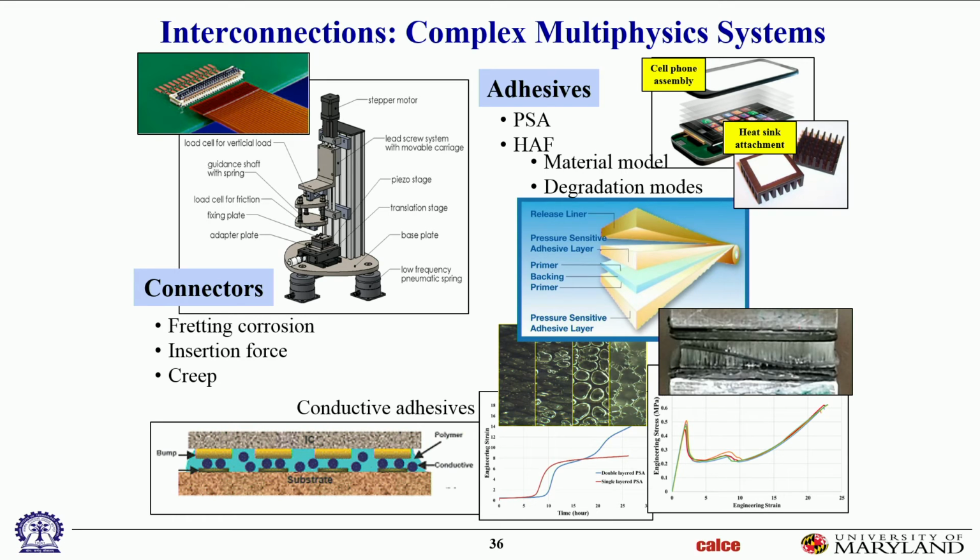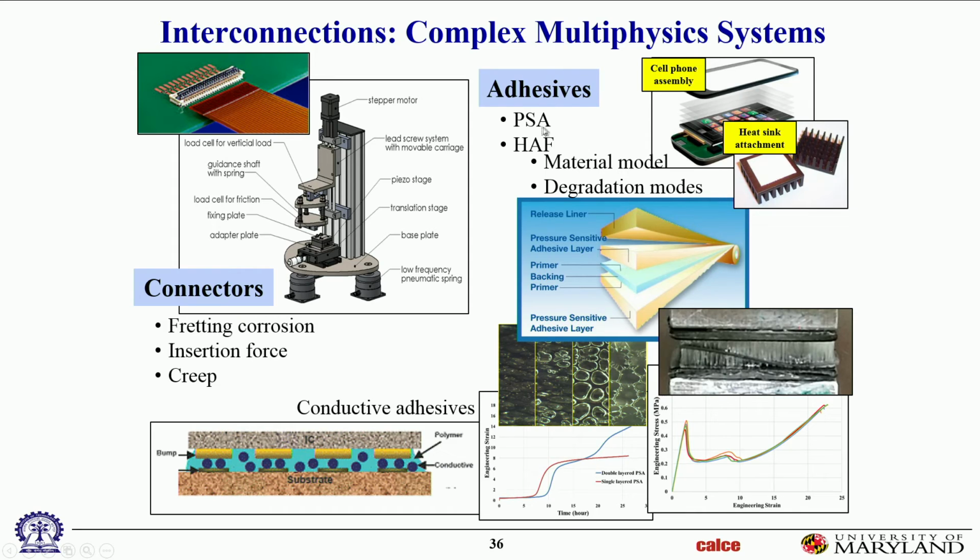The display is mounted in the magnesium case here, not with any metal fasteners, just literally glued in. Your cell phone battery case is just glued in, and they're glued in with what we call pressure sensitive adhesives, PSAs. That means you press it hard enough, they just glue it. It's as simple as that. They cut gaskets of the right shape, place the gasket, press in the display, done. End of manufacture. How reliable is that?